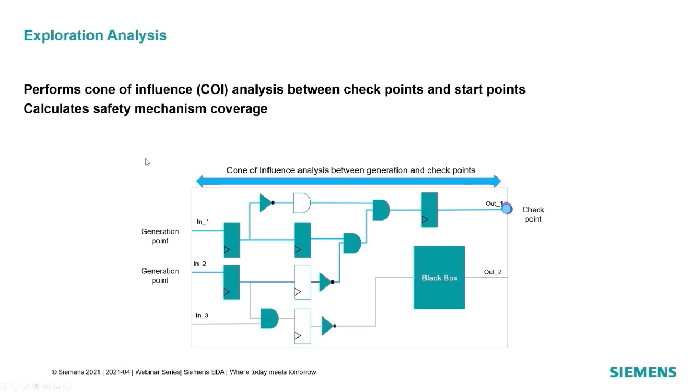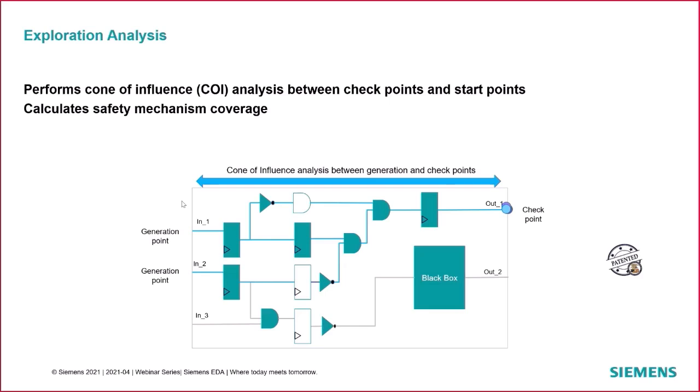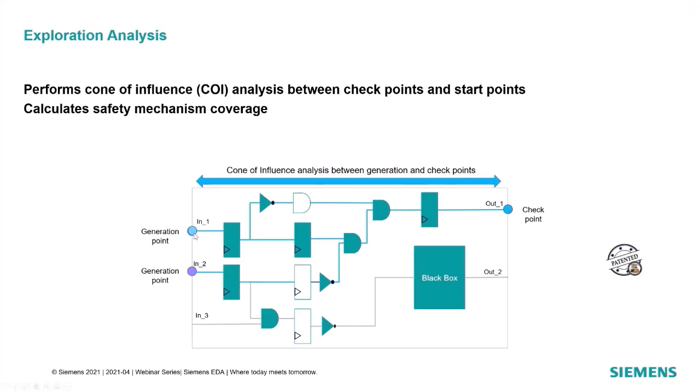So this looks like a really inventive method of getting diagnostic coverage for the design. Can you actually give more detail about this? Yes. This is one of our patented algorithms. What we actually do is take the design into consideration, define the generation points of your data, and define the checkpoints for your data. Just as I showed you before, if input 1 and input 2 are your generation points, we will take these two as the generation points and you can define the checkpoint.